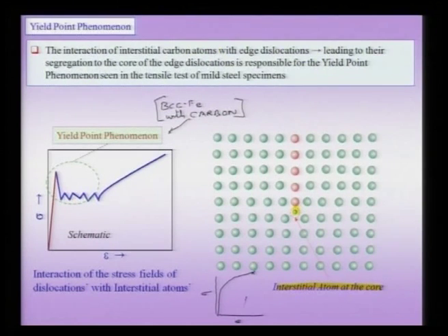In the case of aluminium, for instance, which I draw here, the material will show an elastic region, and then the curve will slowly bend, and that means that dislocations are moving and continuing to cause plasticity. In this case, even though if you look at this overall curve, you would have guessed that the material should start yielding somewhere here, but because of this Cottrell atmosphere, you need to apply an extra stress which is up and above this stress from here to here.